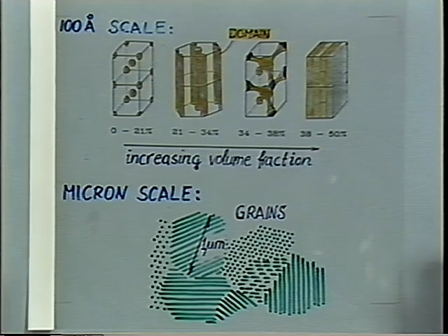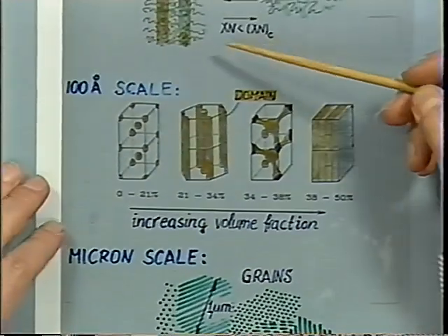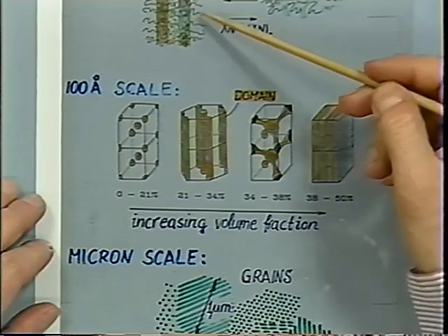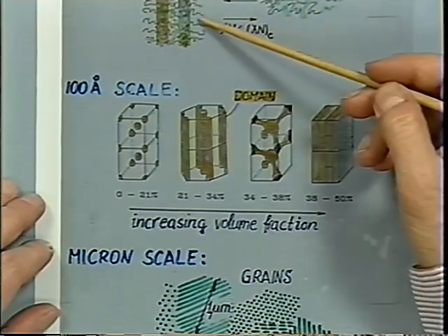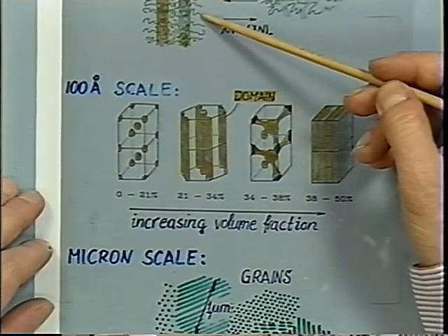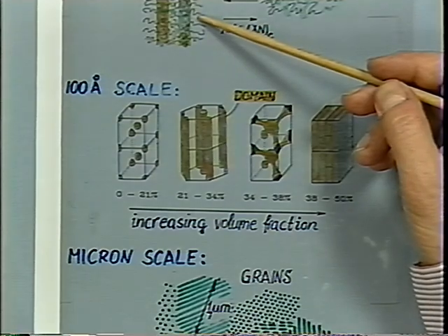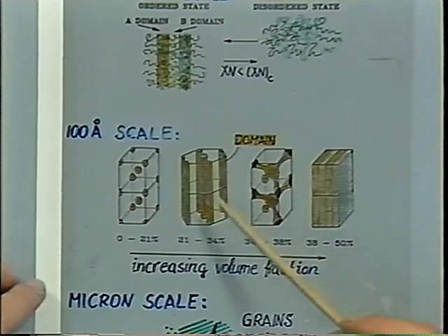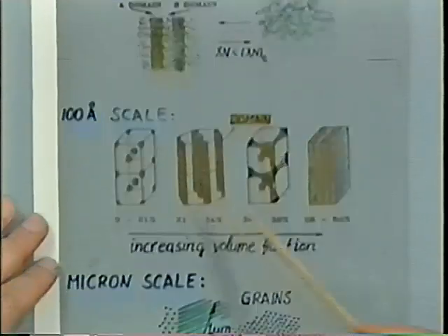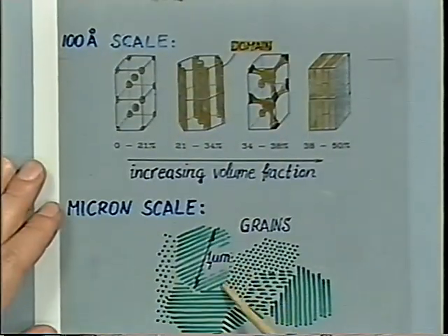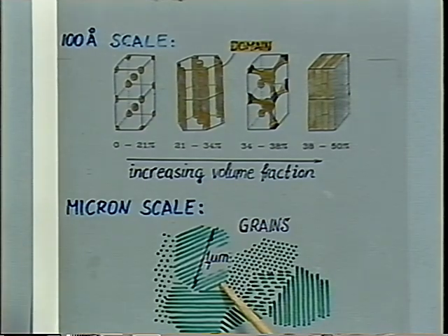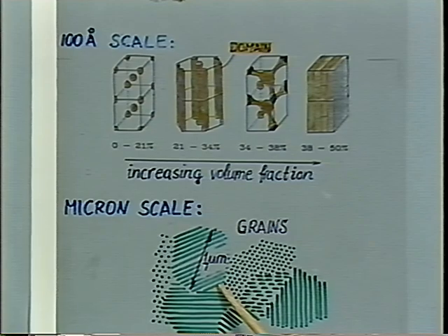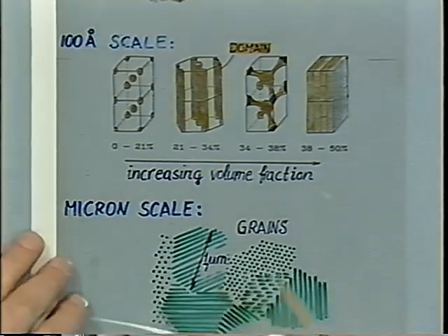In rheology, we see phenomena on all length scales. You will see on higher frequencies, the molecular, the chains, and then going to lower frequencies, longer times, you see the phase-separated structure. And beyond that, you see the regularity of those domains. And you might even pick up grains if you go to very, very low frequencies. So with a mechanical spectroscopy, we can scan all of those.